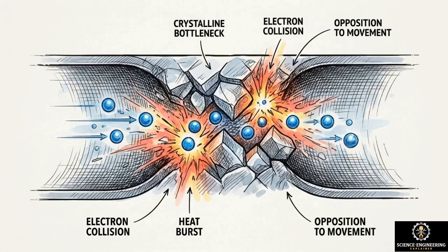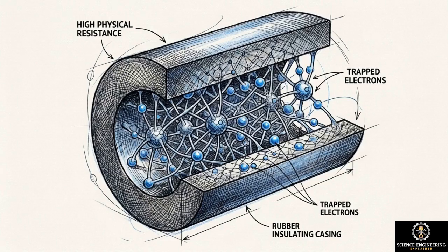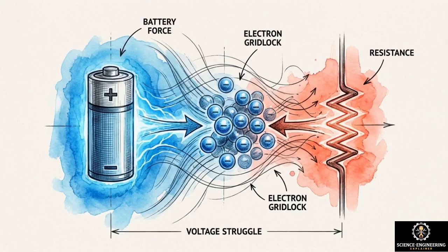As electrons move, they experience friction within the conductive material. This physical opposition is called resistance, measured in ohms. Materials with loosely held electrons, like copper, offer low resistance. Insulators, like rubber, hold electrons tightly, presenting high resistance that requires significant voltage to overcome. The actual flow of any electrical circuit is a continuous physical negotiation. The applied work of the voltage pushes the charge, while the material's inherent resistance opposes it.